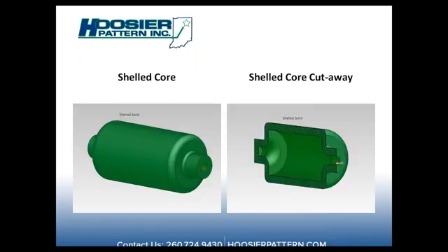A shell core has a called out wall thickness and is hollow on the inside, much like the chocolate Easter bunny. That shell core can have any thickness you want. It can be engineered, and it can have a varying shell thickness that is governed by the topology. This can help in crush and in core cleanout in your shakeout room.